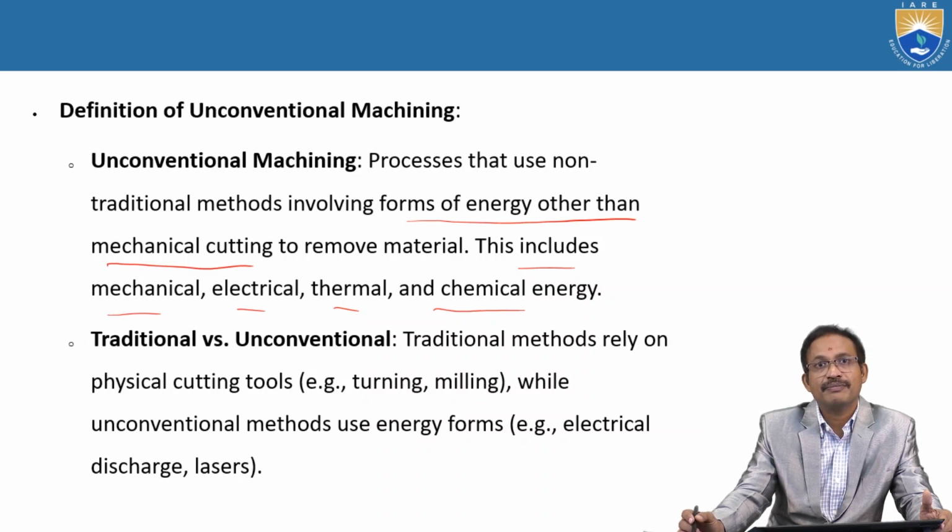Either the workpiece may move or the tool may move against the other in order to remove the material. So some friction will take place, and obviously because of this physical contact and friction, heat may be generated and there will be a great chance of heat affected zones, and subsequently induced stresses will develop.